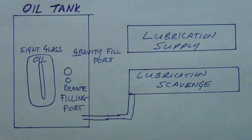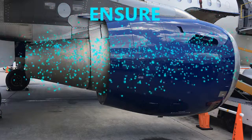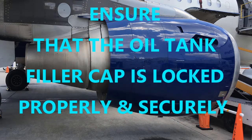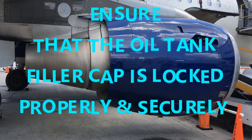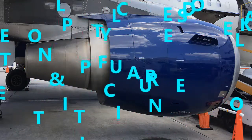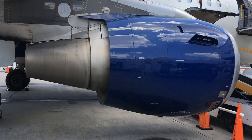Okay. All right, and make sure too that the oil tank filler cap is locked properly, because if you don't, you're not creating that pressurized system or pressurized world there. And if that happens, then obviously there's not going to be a good pressure for operation. Okay, so that's with the oil tank itself, and a little bit about oil pressure.